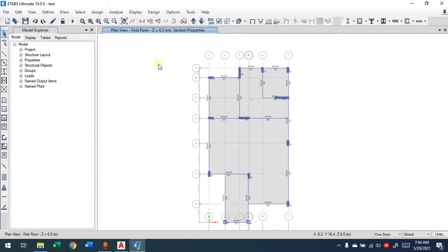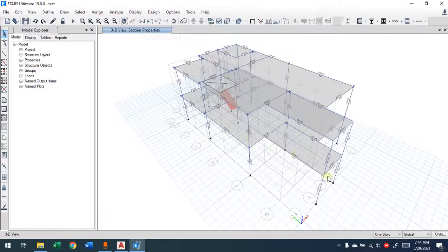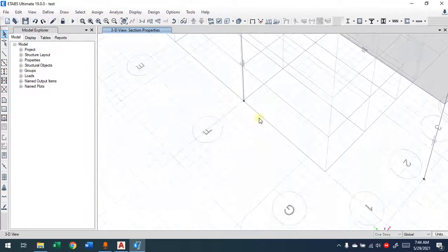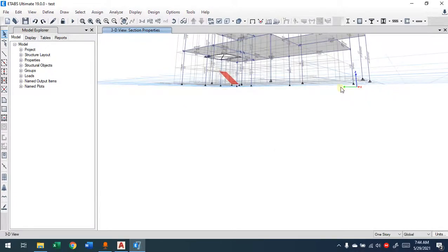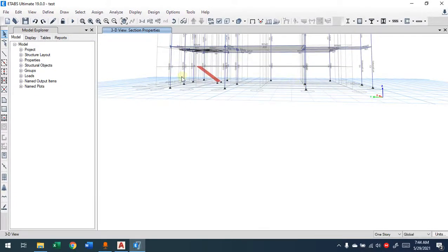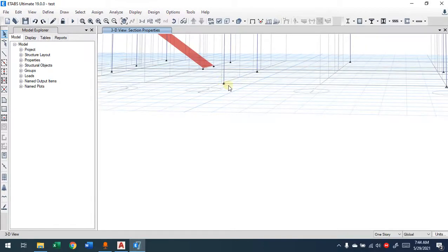First, assigning the joint at the bottom. So if I go to base, now the connection between the columns and the foundation, which is at the base here, the base joints, for example, those joints at the base, yes, I need to make them what? If those will be a mat foundation, those joints will be fixed.